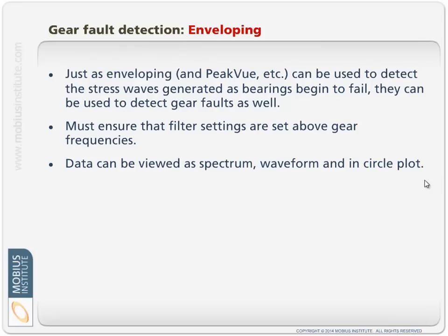But bearings aren't the only thing inside a machine that can cause that impact, which can excite those natural frequencies. If we have damaged teeth, then the same thing occurs. If we have looseness and we're getting a once per revolution impact, the same thing occurs. If we have broken rotor bars, the same thing can occur. The impact is exciting the high frequency natural frequencies, the natural frequencies that exist in the machine up above, to say 2,000 or 3,000 hertz.